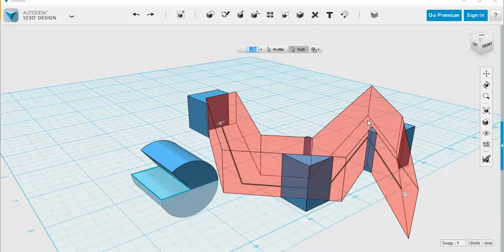You see this really weird red snaky thing coming along. If you look at this dialog menu up here, if we hover over the rightmost side, it will say subtract, which means that all this red stuff is going to cut away all the boxes I previously had on my path.